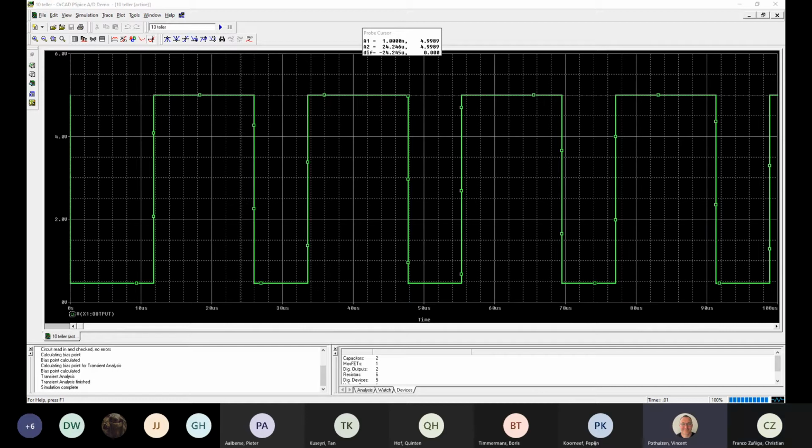Yeah, so you start them. The output signal starts low. You don't look at the beginning, at t equals 0 seconds, because that's the startup effect. You look further down the horizontal line where you can really see that the signal, the waveform, repeats itself. So always go a few waveforms more to the right, then you're really sure. Say about 55 microseconds. Oh, no, that's less. What is that? 48, 47 microseconds.